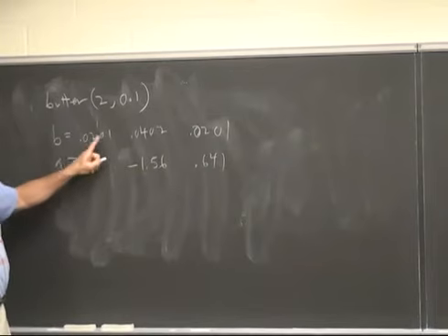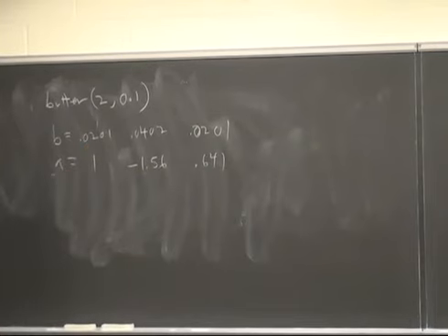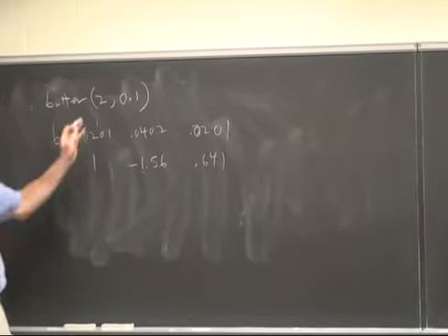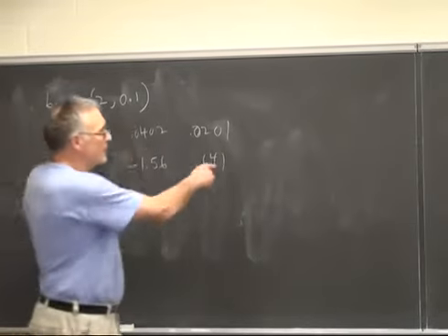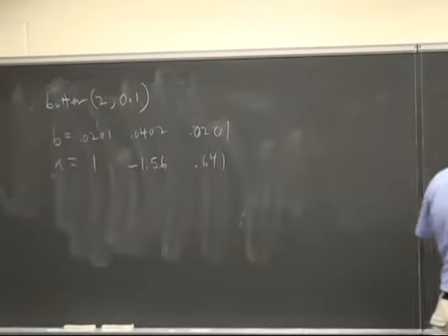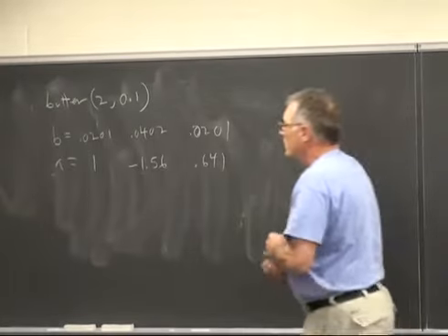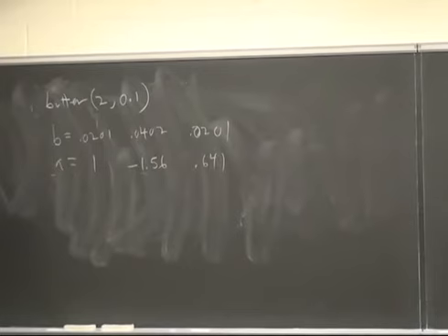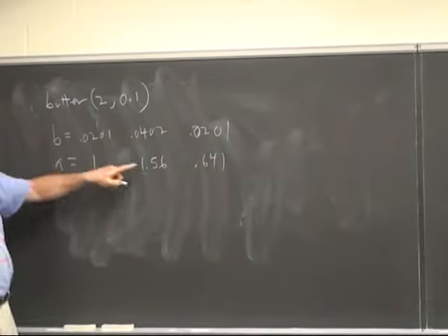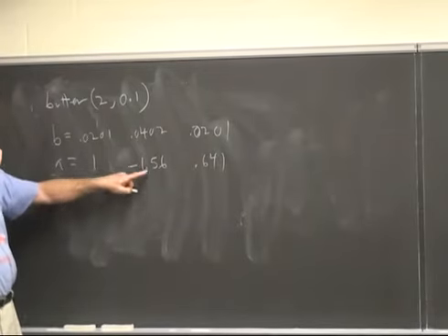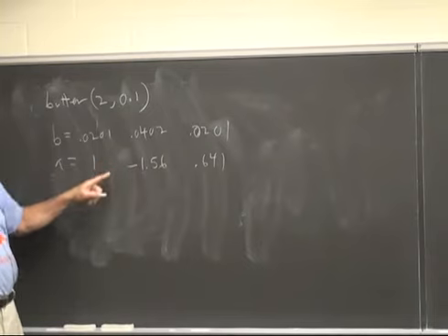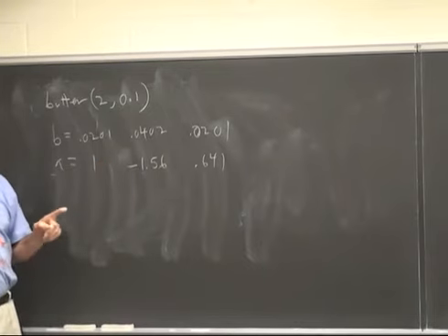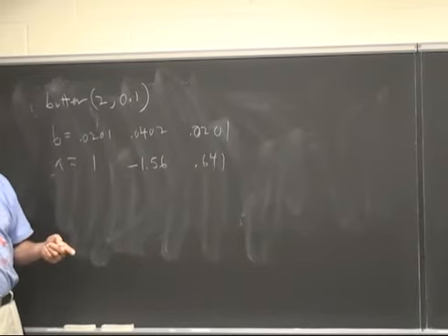And so if we just plugged in the B's here and the A's here, we would have to be very careful about the number of bits we maintain, because an 80 to 1 or 100 to 1 coefficient range means that they differ in size by 7 bits almost.